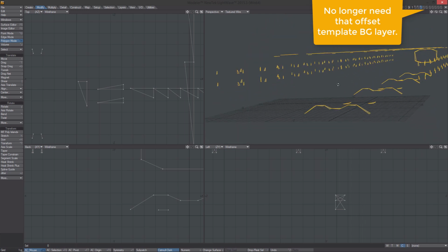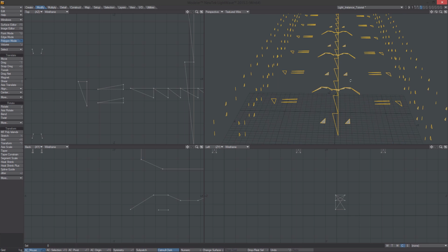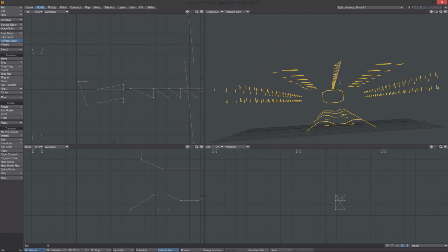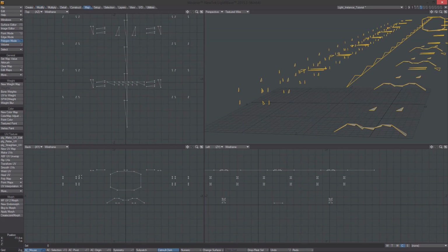And you'll notice for that top long light, I broke that one up into 7.5 meter sections because of the aspect ratio. You don't want to have, the sampling gets bad if you were to leave that as one triangle and have that huge aspect ratio.